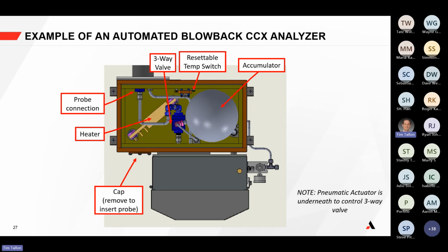And specifically, the one in this case actually uses a pulsing action where it does a big puff and then it pulses. Then it does another big puff and then it pulses. And that pulsing effect provides almost like a vibration that would otherwise hit differently on the filter to blow off any type of dust. So really important to a few elements.